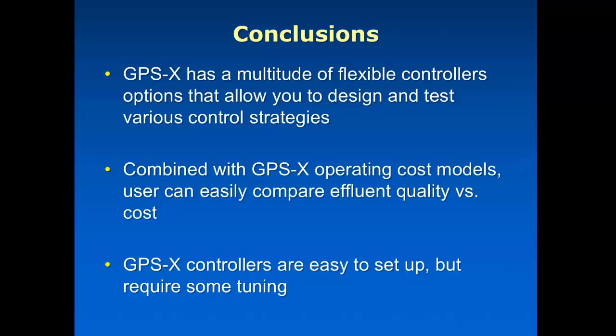And a lot of these controllers are relatively easy to set up in the sense there's only two or three things that you need to do, but the PID control ones are a little more finicky in the sense that you have to do a bit of tuning as well. But that's all part of being able to do process control: understanding how these things work, optimizing those control loops, and trying to find out the best sampling time and the best DO set points and so on. And modeling is definitely a very useful tool in that respect.